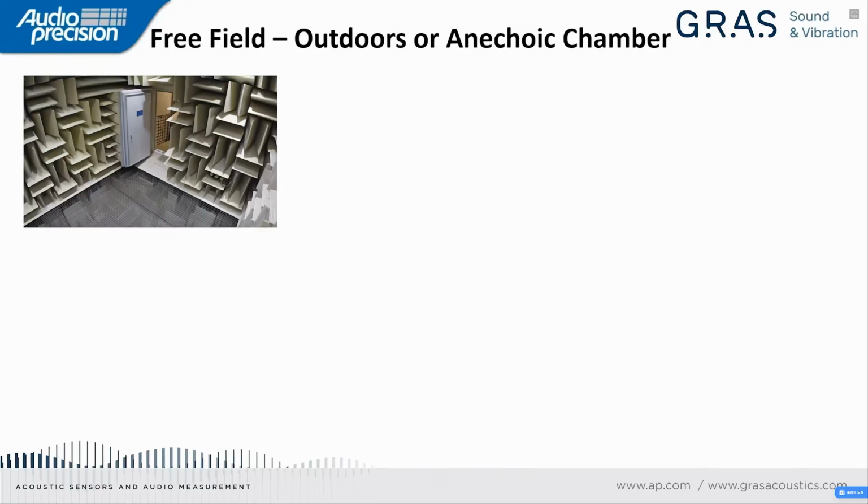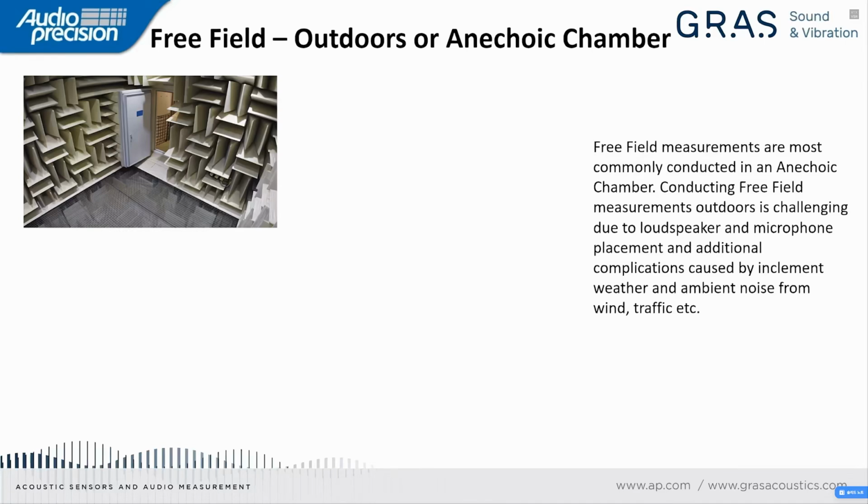So, conducting free field measurements, and in all honesty, you've really got two choices: outdoors or an anechoic chamber. And free field measurements are most commonly conducted in an anechoic chamber. Conducting free field measurements outdoors is challenging due to loudspeaker and microphone placement and additional complications caused by inclement weather, especially if you live in the UK, and ambient noise from wind, traffic, etc.